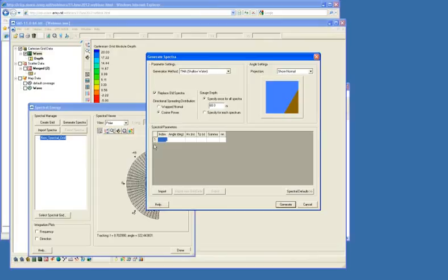And then we start listing these lines of discrete instances of waves. So our wave model doesn't continuously run through time. It's actually modeling one point in time every time it runs. So what we do is we try to get representative wave conditions for certain time periods that we're wanting to simulate.